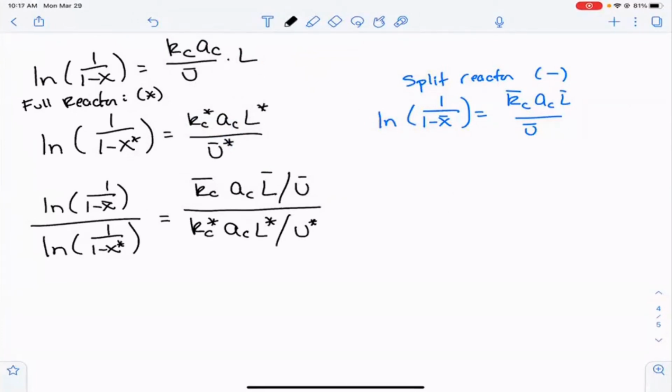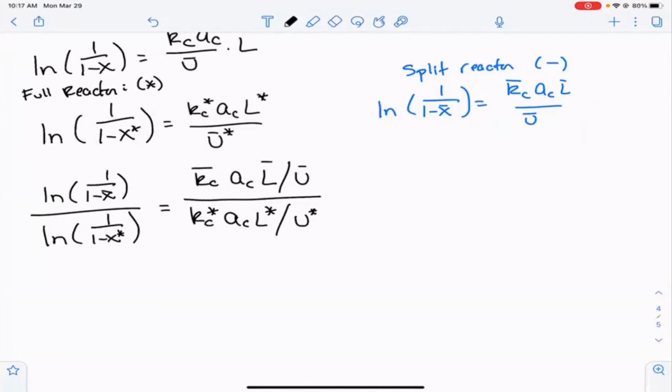Now, looking at this, you might think all the terms are going to cancel. But remember, we just said this in the last lecture. We know that's not true, or at least we would think that the Kc's might cancel. But that can't be true because Kc is equal to 0.6 times dAB to the 2/3 over the kinematic viscosity to the 1/6 times U, the velocity, to the 1/2 over the diameter of the particles to the 1/2.